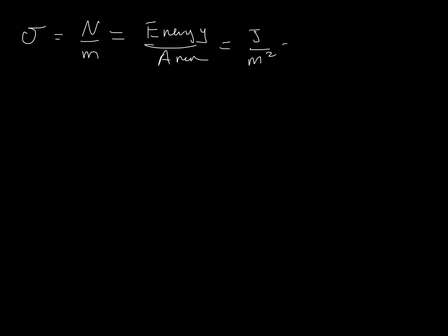So the SI units of surface tension are Newtons per meter, and we typically write it as sigma. Right, so we can relate this back to surface energy. I'm going to say that this is the same thing as an energy over an area. So energy is joules per meter squared. A joule is a Newton meter, divided by meters squared, and that gets us back to our SI units of